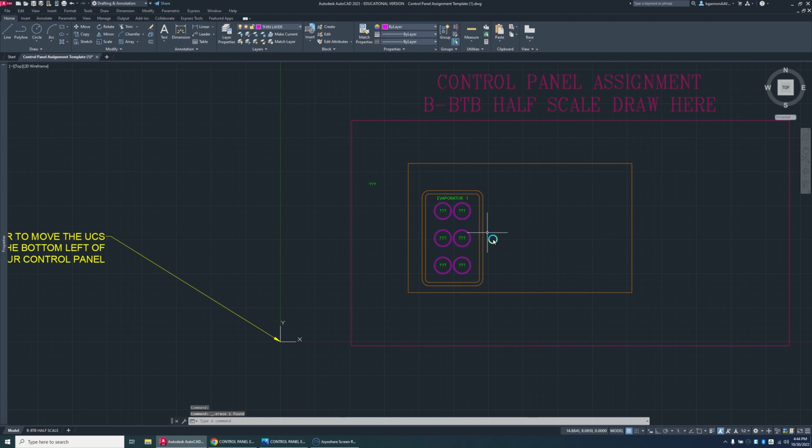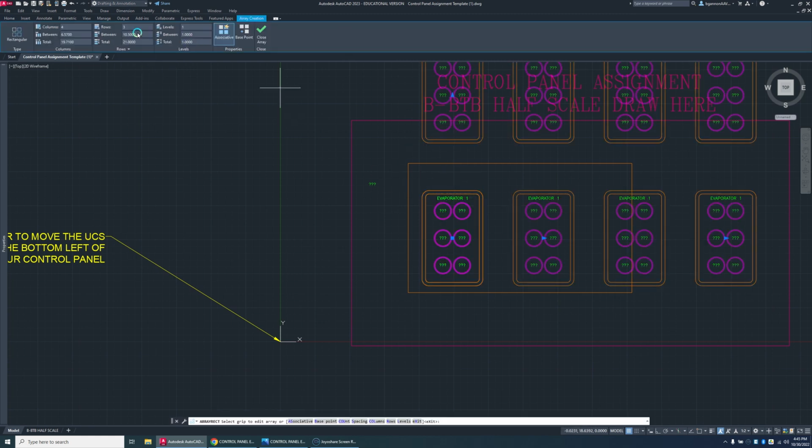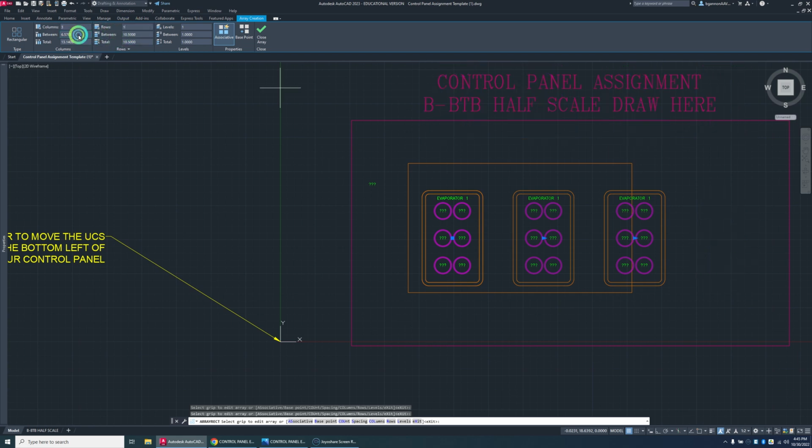Okay, next here, there's multiple ways to do this. I can offset this here, copy it all and offset it by points. And I'm actually going to use the array tool to make this happen. So I'm going to select it all and then go to my array tool, and rectangular array, so not polar array. I want 3 columns and only 1 row. And the distance between everything, I believe, is 4.38, if I do quick math in my head.